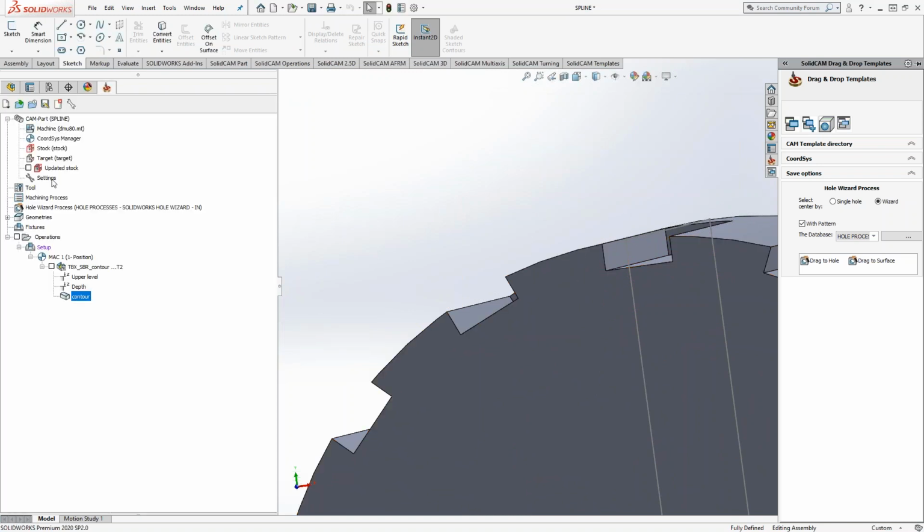I was thinking if the arrow was going the other way, what we could do is do that straight line and then add just like a little tangent arc at the end. It doesn't receive anything other than just the straight line. So like the previous example, because it had those fillets on it, it's not like I could choose those fillets. It wouldn't follow that shape. It just does a toolpath that looks like that.